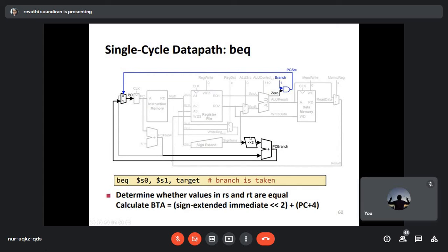In a branch instruction, you would have understood that it is branching out to a target value. So you have the signed integer. You will shift by 2 since your address should include your signed values. Again, you have an addition operation here, addition to your program counter value, the address.